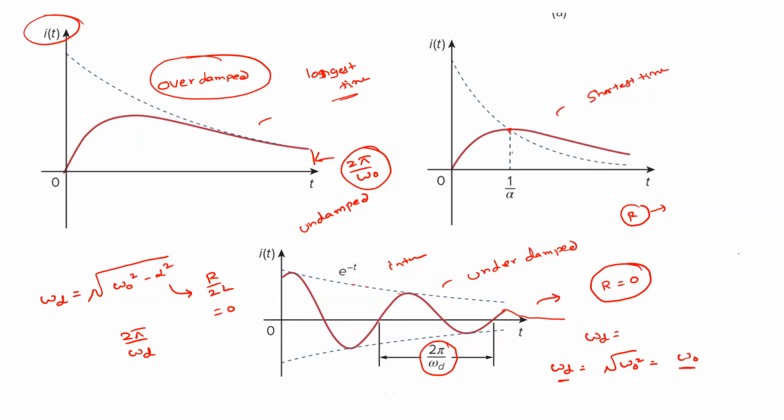Let us assume this is 1000 volts, and in a few cycles it has reached 2 volts. What will you say? Practically it has reached steady state, right? Theoretically it requires infinite time, but practically it requires some finite time, close to the final value. Usually a 1% or 2% approximation is used. For example, if 1000 volts is the peak value, then 10 volts is fine, and we treat it as 0.